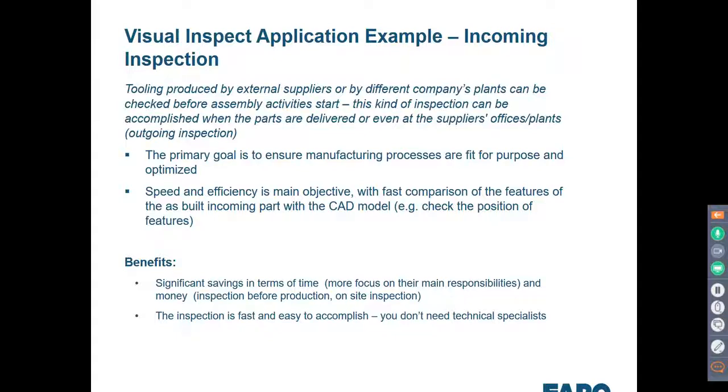Sometimes it's not just an overt event where we have to scrap something, but it's a rework situation. Let's say you're using a shadow board and you're putting up 40 weldments on an assembly, and all those items are there. All the operator knows is that, okay, I cleared my shadow box, I have everything in the kit that needs to be put up, so I've done my job. However, what if there's something that hasn't had a hole drilled properly, or a hole is missing? That's going to cause a lot of pain and suffering further downstream. And this is one of the key areas where we can mitigate or reduce that level of pain.